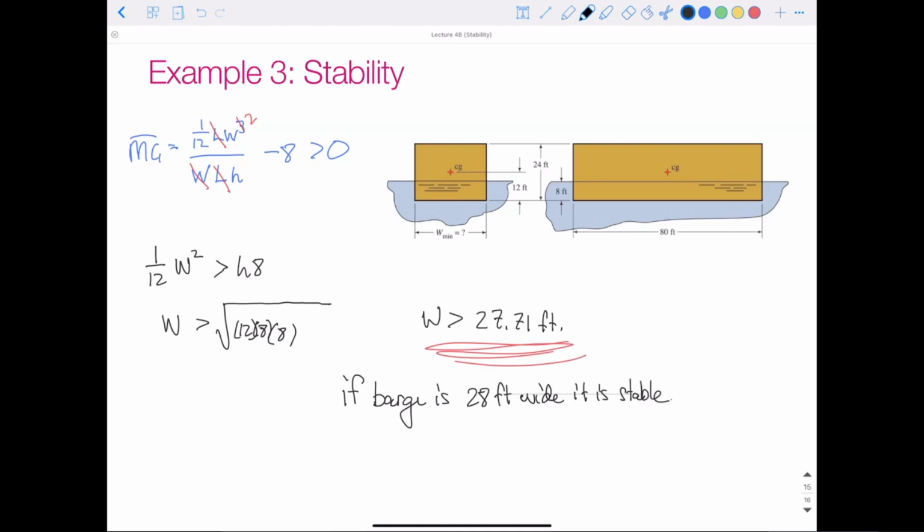the metacenter is at the center of gravity. So if we tilt the body at all, that means the center of buoyancy remains directly below our center of gravity. So that line that we draw vertically upwards from our new center of buoyancy stays directly below. So the only shape I could think of offhand right now that fits that description would be a sphere.